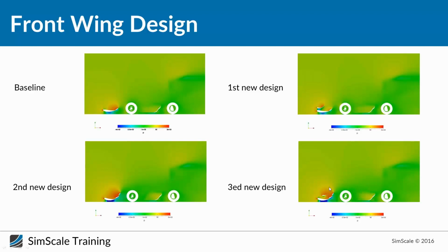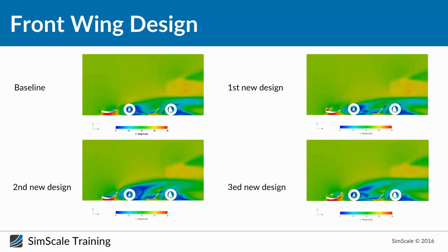So from now on, guys, make sure you take into consideration that adding any element on top of your wing will reduce the pressure on top of the front wing, because you will have a suction under your element, or cascade element, or any kind of element that you add on top of your wing, and in consequence this will reduce the downforce.